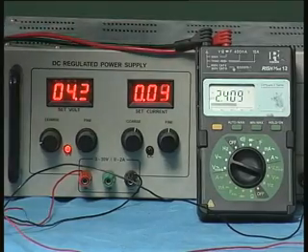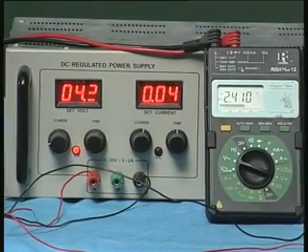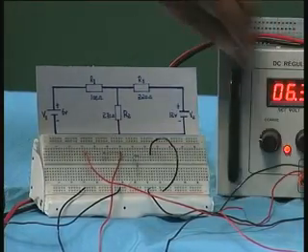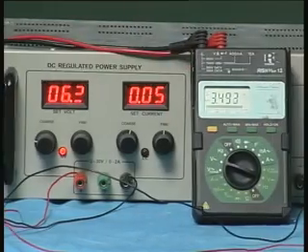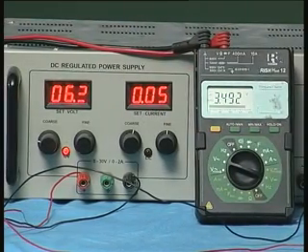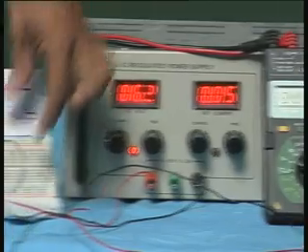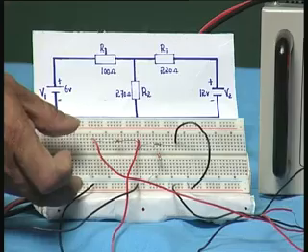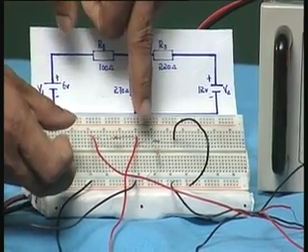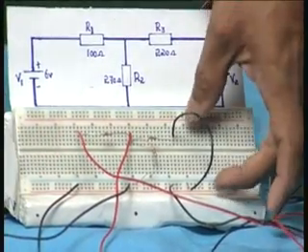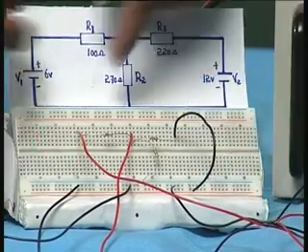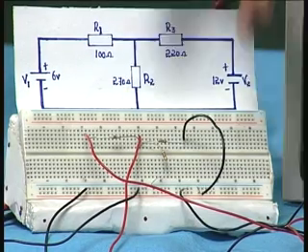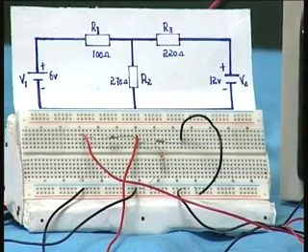Now I will measure the voltage here, it is around 2.4 or something, right? Now it has come down, is it? Yeah, 6 volts. Now it is about 3.5. So 3.5 and 3 gives around 6 point something. So that is the voltage we got when both the voltage sources were connected together. So superposition says that you have only one voltage source, find out what the voltage across R2 is, and remove this and connect the other voltage source. Here you connect it by a short and measure the voltage, then you add them together, you will get the total voltage which you will get when both the voltage sources are available. So this has been very easily shown.